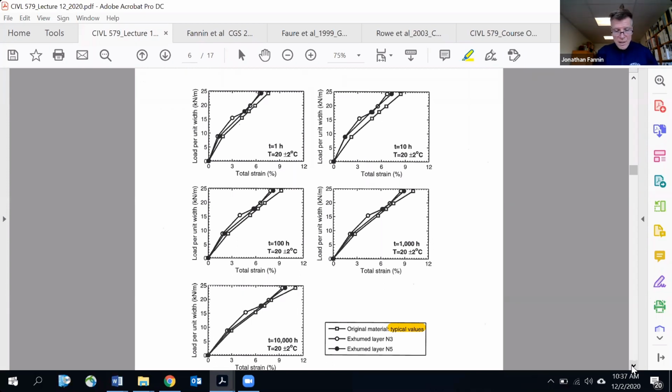I look at that and say, after 25 years, not only is the geometry of the grid apparently comparable to the original material, not only is the quality control load strain testing, let's call that index testing, good, but the careful controlled isochronous load strain curves are good too. So that's a rip-roaring success story. And why? Because do you remember there are these 3 case studies, and we're about to break for the middle one. But remember I said there's the good, there's the not so bad, and then there's the ugly.